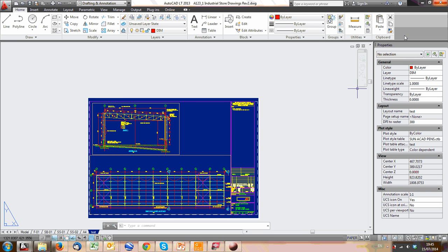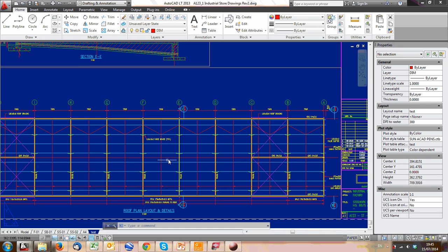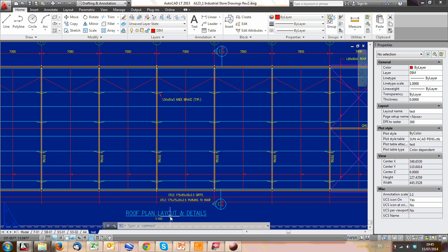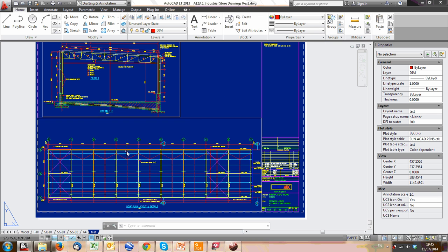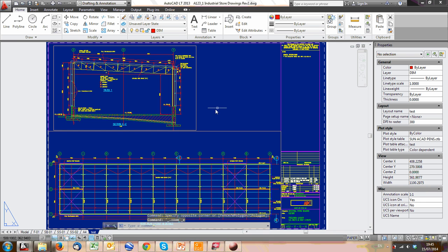Normally when you set up a drawing though, you'd have this template from the beginning, and if you're unsure of scales, for instance, what scale do I draw this at, and you know it has to fit on an A1 or an A0, you could create a viewport and quickly check, or your grid lines, do the grid lines fit on whatever scale, 1 in 100, 1 in 150, 200, etc., and then do your drawing, do your dimensioning and your text at that scale. So that's an easy way to work around that problem. So you know in advance, you don't draw this whole layout only to find all your dimensions and your text and the rest is wrong and you have to redo it.